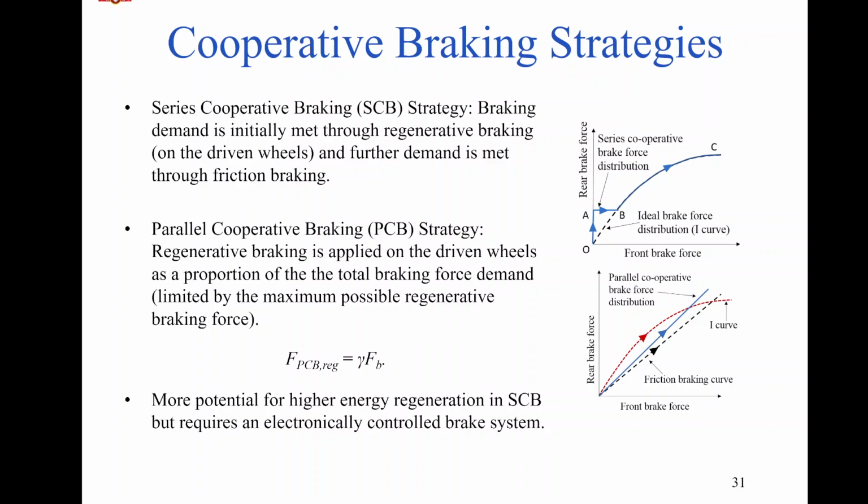Sir, is regenerative brake a disc brake or another brake? No, in regenerative braking you use the motor inside the electric vehicle. You have a motor in your electric vehicle which you use for driving. The same motor you are using as a generator, or brake. If you are using it as a generator, that means you are converting the energy of the motion of the vehicle to electrical energy.